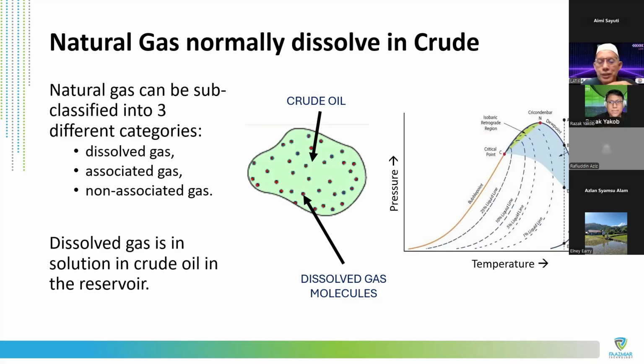with a slight compression. For example, if it is 1 million at the bottom, and then as we come up it is about 950 thousand pounds, maybe just a bit less, about 5% compressibility. So that's how the gas dissolves in the crude oil, goes to surface and is released. So you have gas and oil production at the top.